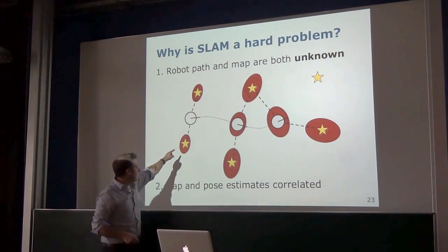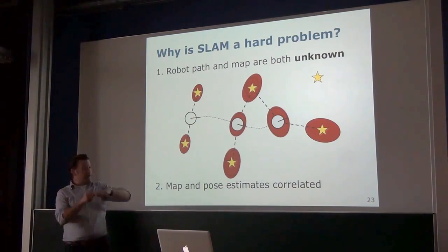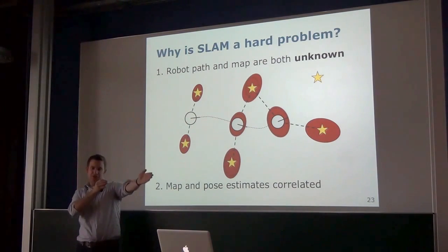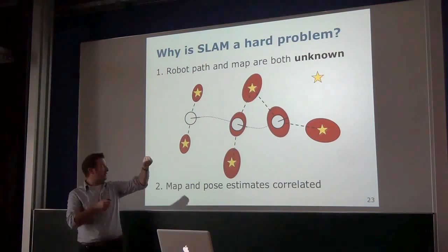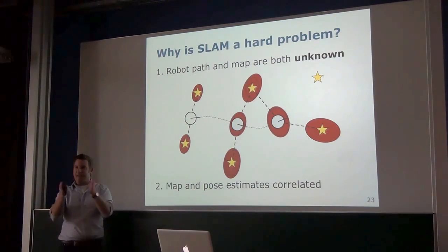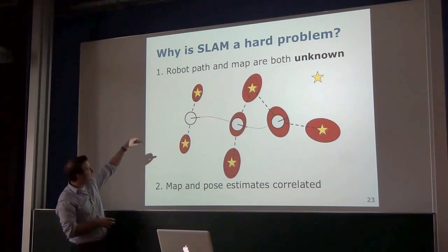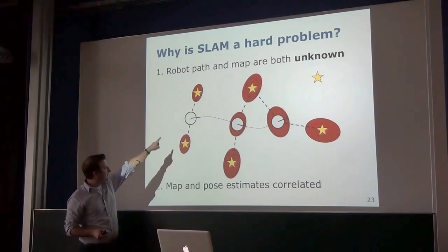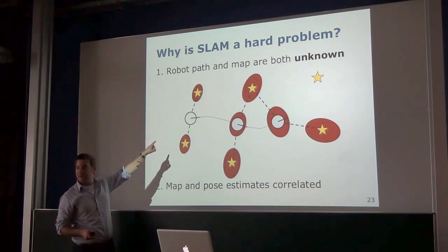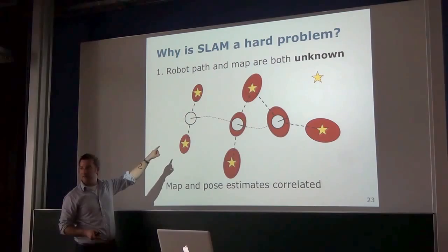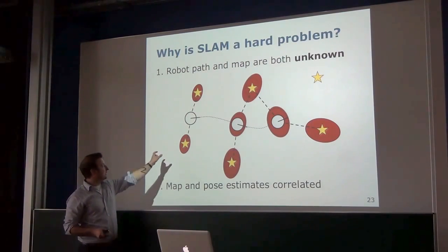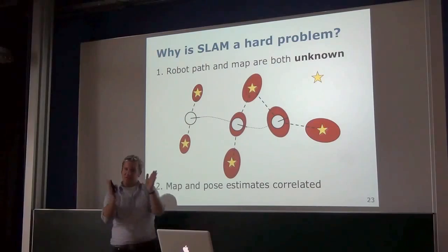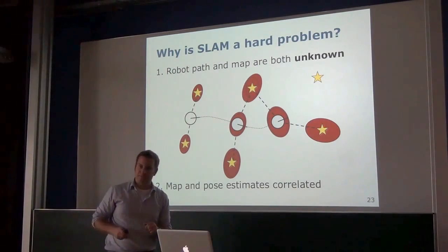Because you can see here, in this example, I had a bigger uncertainty in the direction which is the proximity to the landmark, and I'm more certain about the angle where the landmark is relative to the robot's pose. There you see these ellipses are along the line towards the robot. So it's less accurate measuring the proximity to the landmark, and more accurate in terms of the angle. And therefore the shape of this ellipse changes.